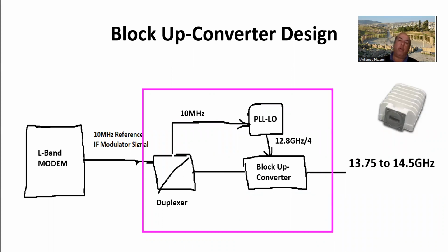Let's see how we go about designing one at the system level. This is the stage where you're trying to design the architecture, align the signals, pick the components, and at the top level, without going into final discrete components, you design it and verify it using system design tools, such as the one I'm going to be using today, which is the Pathwave SystemVue from Keysight Technologies. So here's the BUC up converter, in this colored box here.